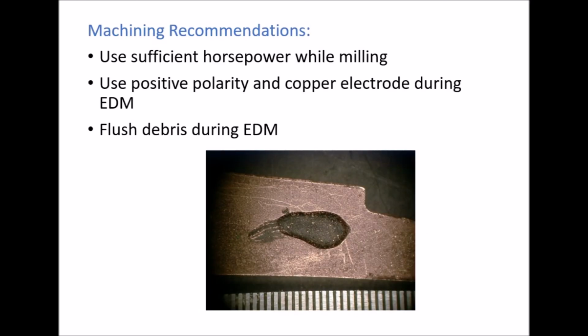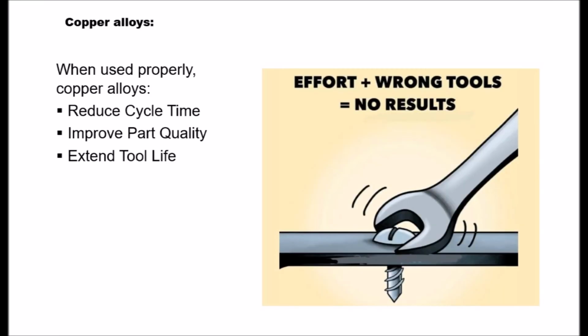Use sufficient horsepower while milling. Use positive polarity and a copper electrode during EDM. Flush debris during EDM. Copper alloys, when used properly, reduce cycle time, improve part quality, and extend tool life.